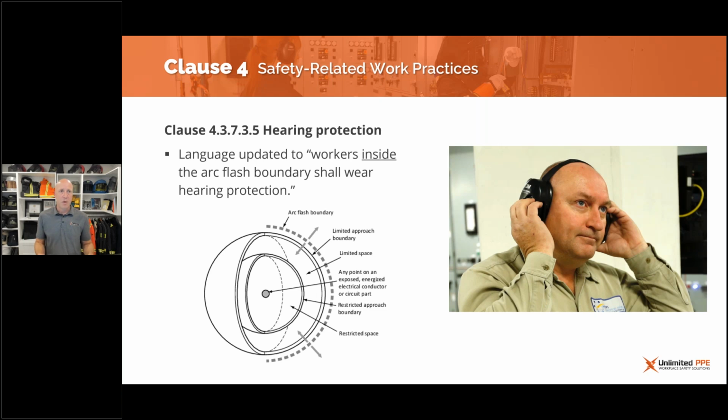So if you have your cover removed or door opened, that is a way of mitigating arc blast. We also know that any blast is attributed to the short circuit fault current, but the fault current is only one part of the equation for how we calculate incident energy. So therefore, incident energy and blast do not correlate. The actual incident energy has a lot more to do with the clearing time of your protective device upstream. So you could end up with very high blast potential, but low incident energy because of the clearing time.